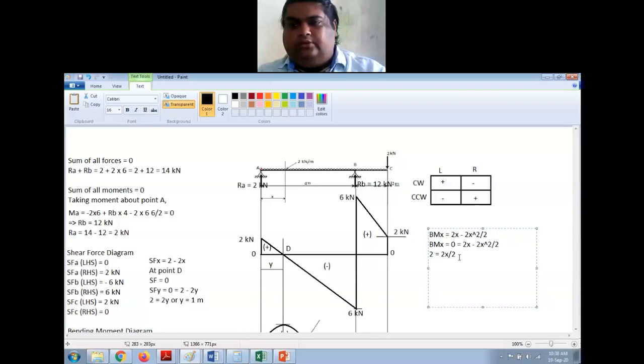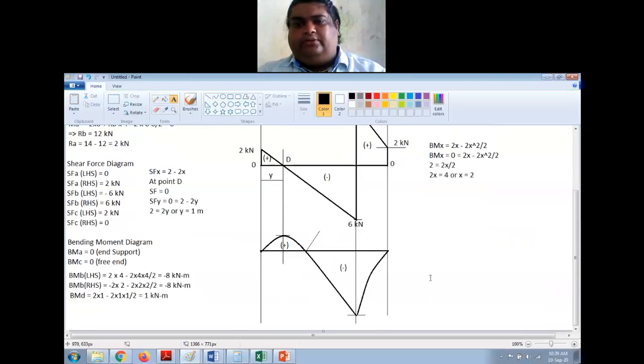Yeah, just a minute. That's what even I'm getting here. So from this I can write 2x is equal to 4, or x is equal to 2. What did you say? X is equal to 0, or did you get 2? Yes, sir. Yeah. So it is at the midpoint of A and B. I have the point of contraflexure, right? So why this point is important?